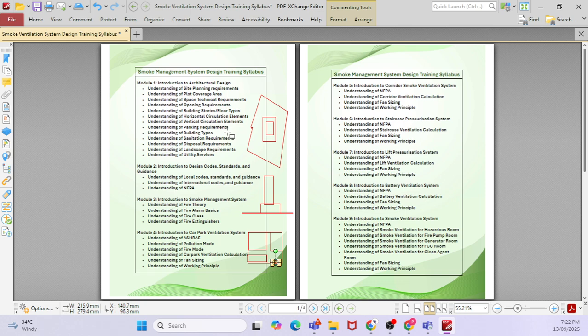Definitely, so there is a clear understanding, because if the MEP person or the architect has a requirement, okay, what is the minimum false ceiling requirement, then the person will understand easily. Okay, this false ceiling cannot go down, so he will adjust the MEP services, and he will have a clear idea of how to design the MEP services with respect to the architectural design, right?